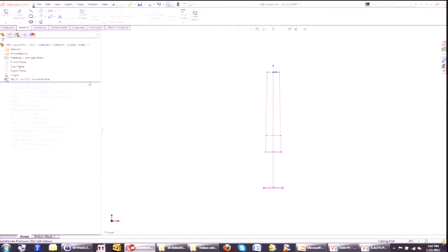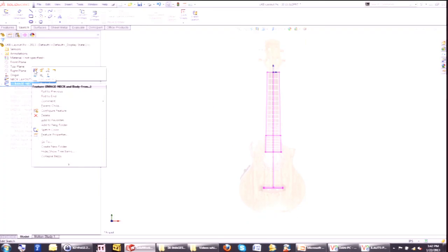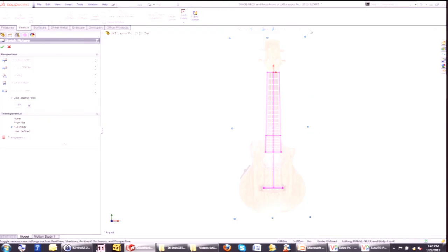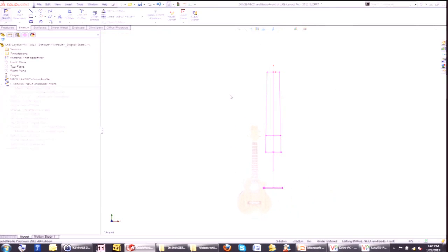And once I had that information, I was able to use the command Sketch Picture and bring a picture in. It's not going to come in the right size, and it's not going to come in the right angle. So within that sketch, you just start dragging this thing around until you get it to be the right size and the right angle and everything. So let me see if I can cancel that. Discard changes and exit. Okay, good.